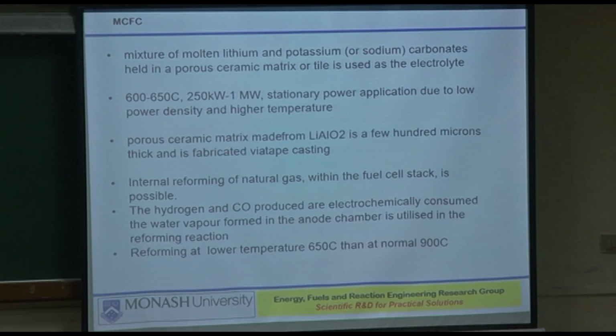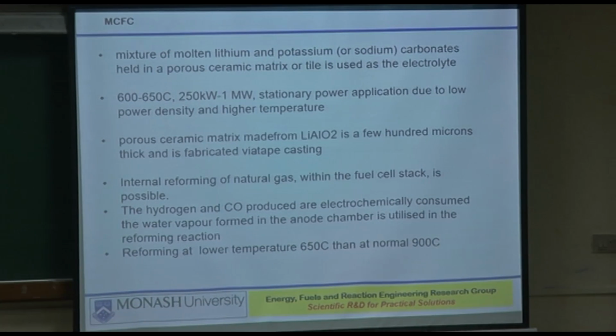So these are available up to 1 megawatt, but I have seen Westinghouse's, Siemens' offering of a 2 megawatt unit as well, a single unit, so quite large. A porous ceramic matrix made from lithium aluminate is a few hundred microns thick and is fabricated via tape casting. The reason I wanted to show this one is that sometimes you may think that these are very difficult to make.